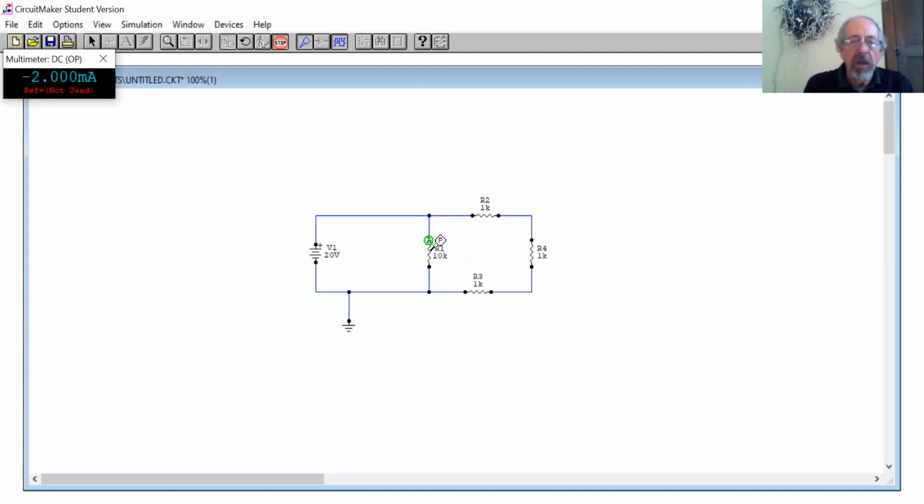And I didn't mention here power. The probe goes to a P and actually tells me I got 40 milliwatts of power in that resistor. Or if I go over to the battery, it tells me I got 173.3 milliwatts going to all these resistors here. And each resistor over here, what do we have? 44.44 milliwatts. Again, all kinds of calculations are done automatically for you. You don't have to do all the paperwork. That's kind of nice. Okay, so that's DC.